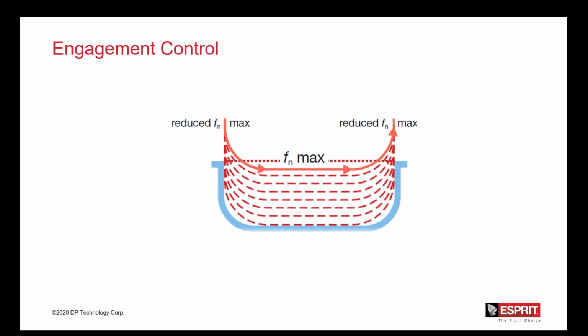With the smooth roll-in movements and using a smaller feed rate, the cutting force at the tool entry is significantly reduced, and it's maintained at a consistent level. The feed rate is also maximized during the straight line movements. So once you're in the cut and you have that straight line movement, you can then ramp up that feed rate along those parallel moves. And while it's doing that, it's still maintaining a constant engagement, and then we'll reduce that engagement when we're exiting the cut. So that's how we manage the engagement control there. And we'll see options as to what we have there within the operation. We're going to take a look at that.